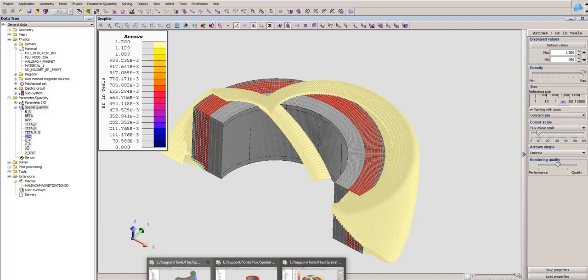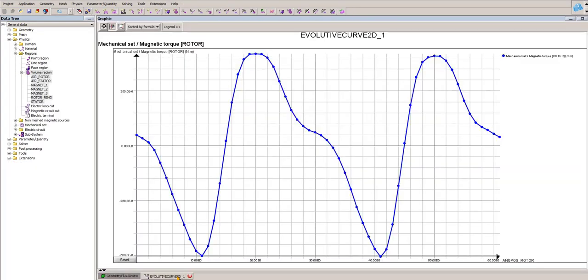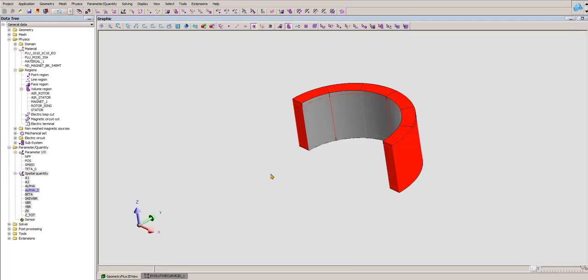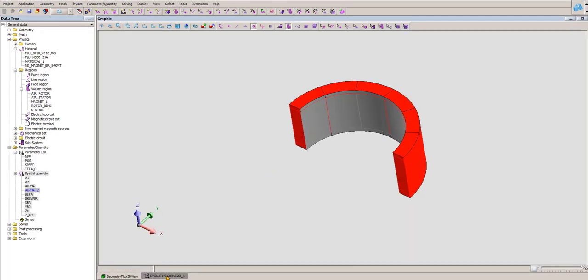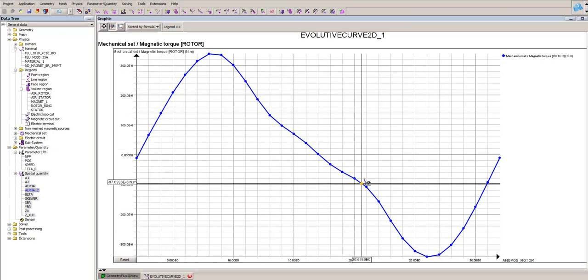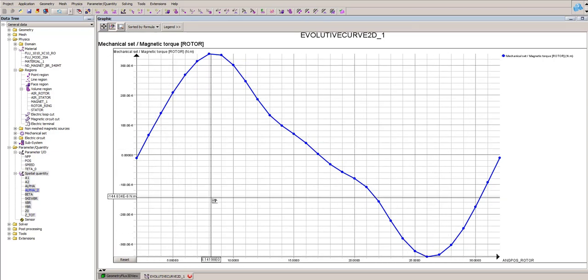So if I come back once again to the cogging torque I had with radial skewed magnetization, this is it. As you can see, it's not really symmetrical. But when I use a spatial skewed magnetization, I have really a symmetric cogging torque, which is what is expected in a rotating electrical machine.